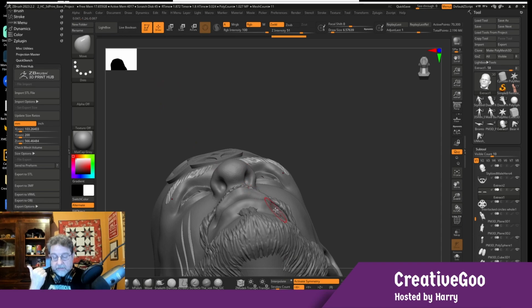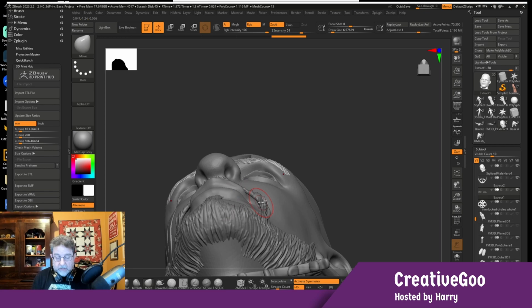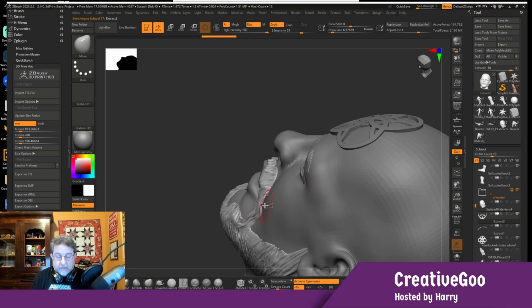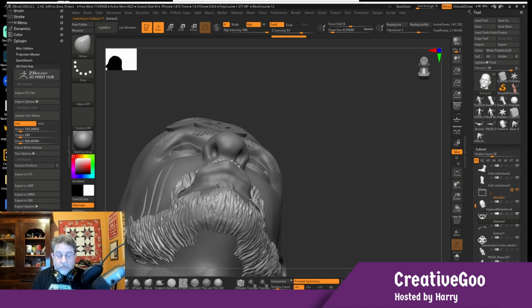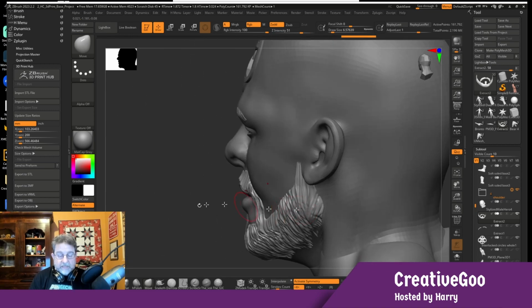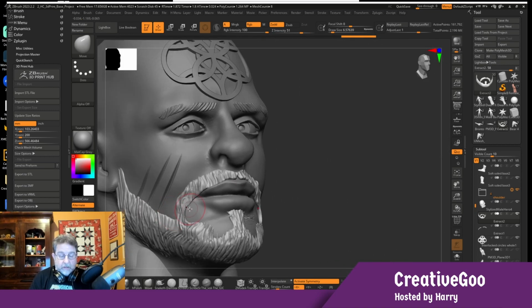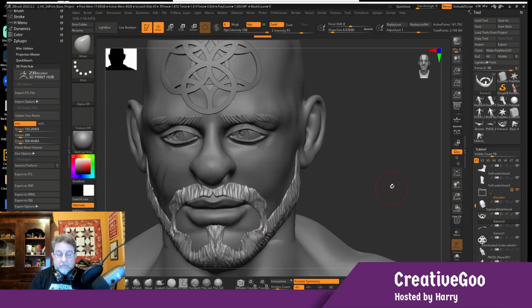And you can see underneath the mustache here, I probably have a problem. So I'm going to have to go through and fix that. His mustache is pulled away from the face, and that would be a problem because it's so small you might not notice, but a really good printer will actually print that piece, and then it'll break off, and it might be floating around in your resin and then cause problems later. Those are things you don't want. So I'm going to mess with this later so I can print him, but those are things you need to look for. I'll probably thicken it up on the inside, but those are the face things.